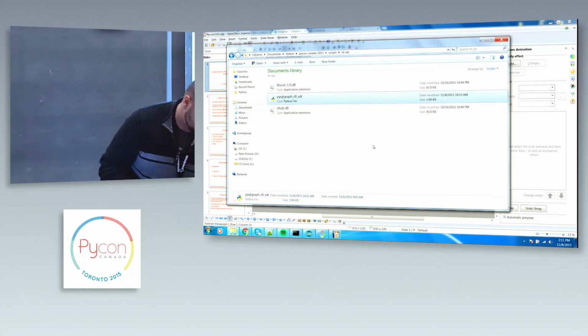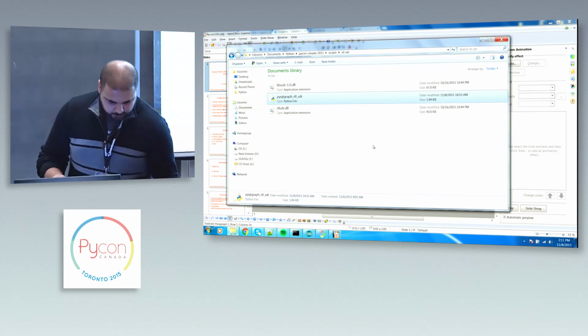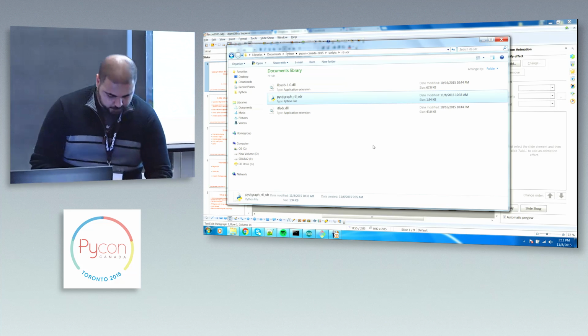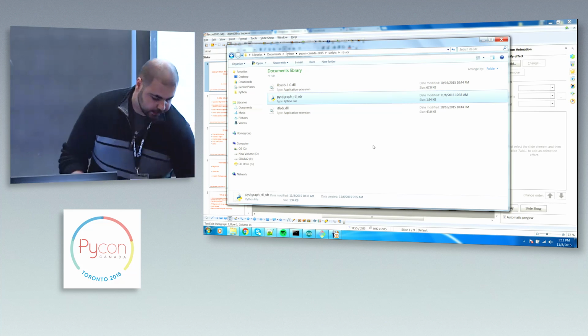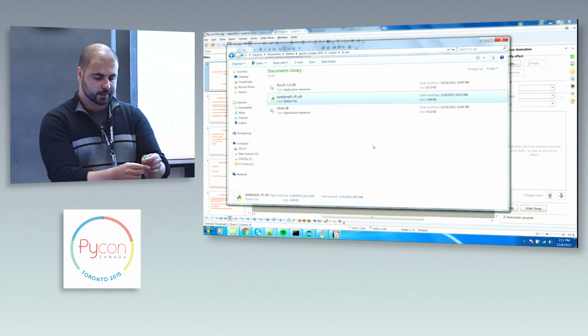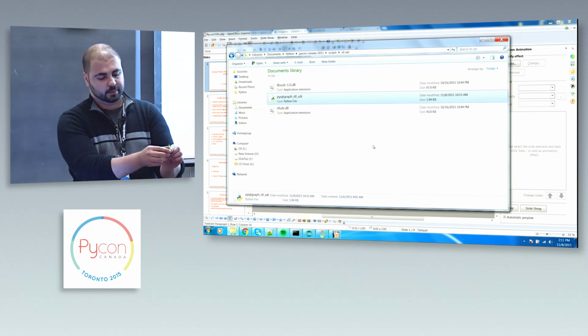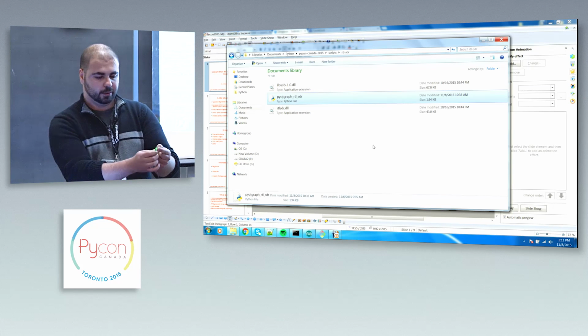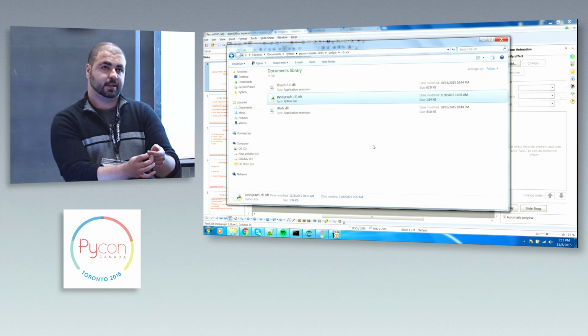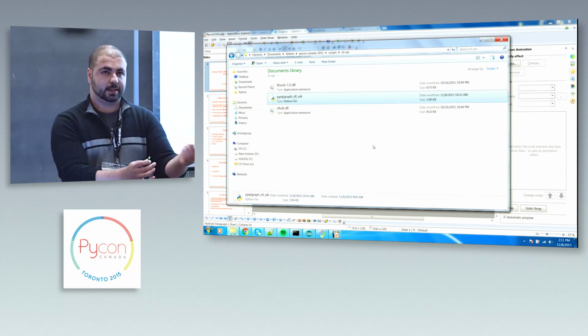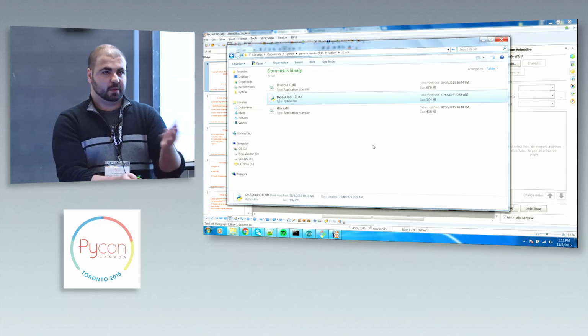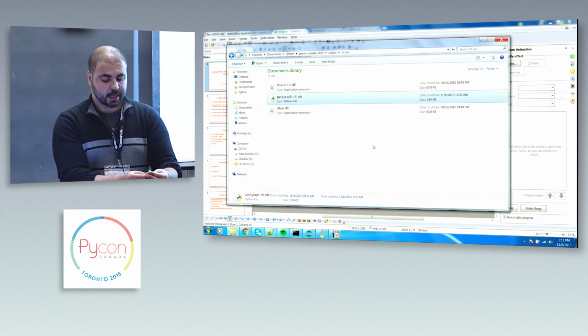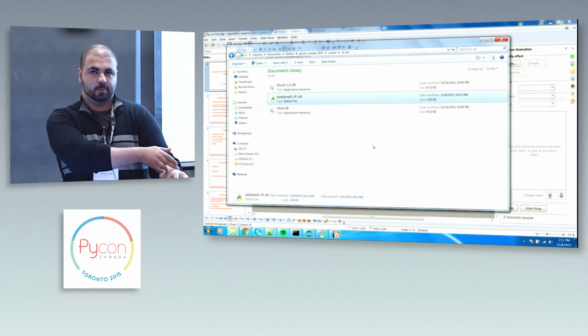The next demo I have is a pulse sensor. So I'm going to be sensing my pulse. Just got to connect this. So again, in this case, the sensor here is this little guy. It's emitting a light. And I don't know if you guys can see it. That's the light. And that light's going to go through my finger. On the same sensor, there's a photoresistive transistor that's going to read back the light. And basically, that light's going to change every time my heart pumps blood into my arm.